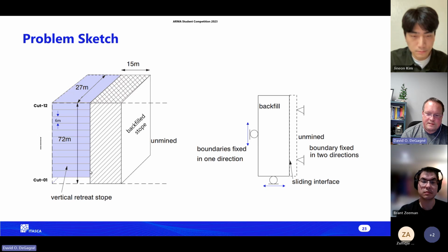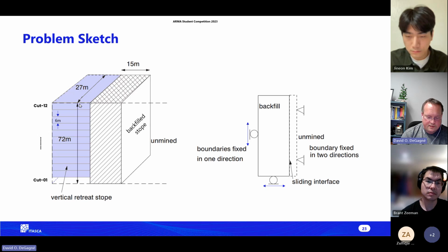This is a relatively large dimension. If we were to remove everything instantaneously, there would be a sudden redistribution of forces, and the model could behave dynamically, and we would get artificially induced damage. It's almost like, if you've worked with a testing frame for UCS tests, those use a very controlled closure rate, depending on the material.